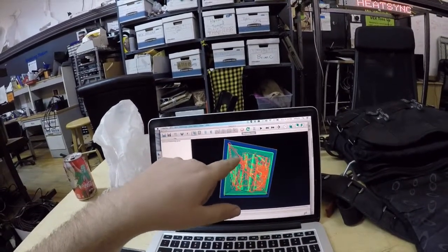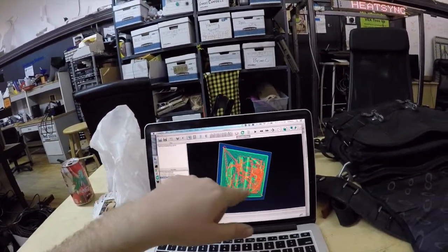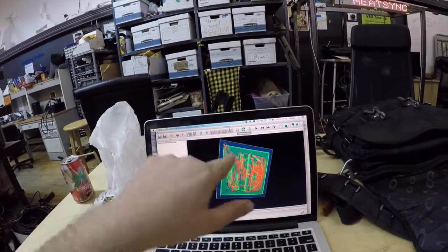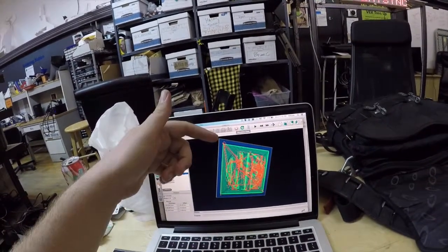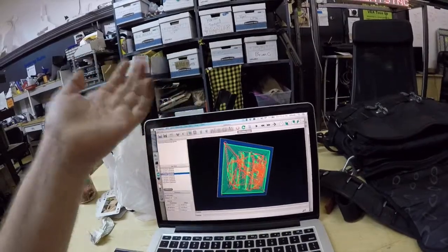Now, I want to cut out this stuff here, but all these other passes I don't care about. This is basically a face cut, basically to clean the face of the material to make it look nice when you're finished. But I don't want that, and it's going to take a lot of time on the mill. So what I might try and do is basically just sit there and watch the mill and then cancel it before it gets to that step.